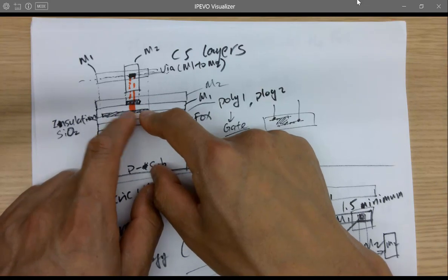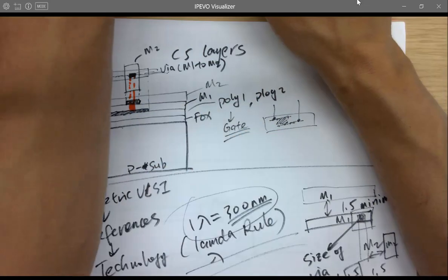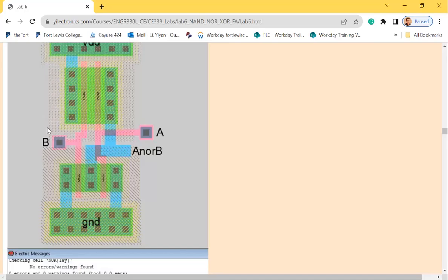That's a gate. It's a gate of the transistor. You need a signal to it. Make sense? So that's why in here I know it's metal 1. So this little contact is metal 1. The via is going to be the poly to metal 1 via, right? So that's why this guy cannot be too close to it.